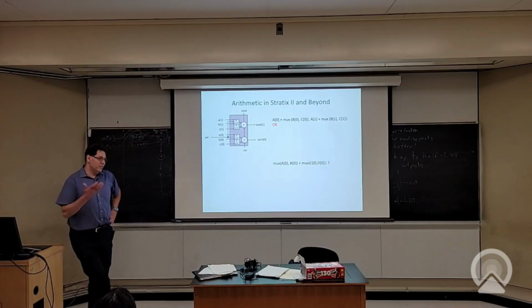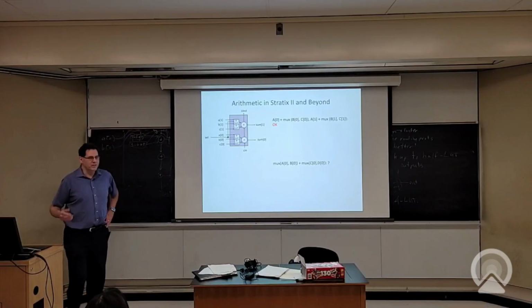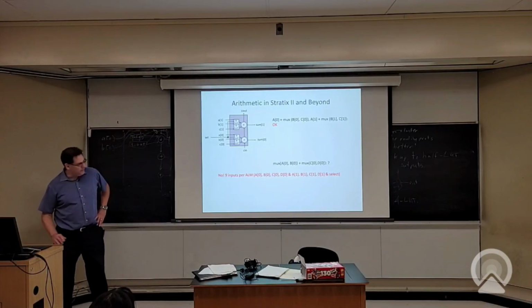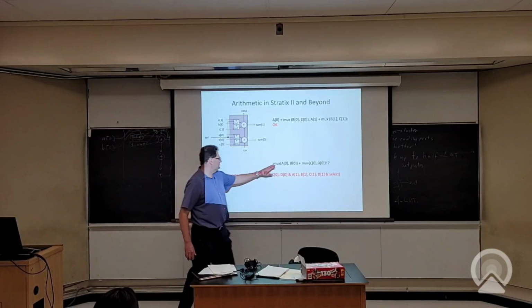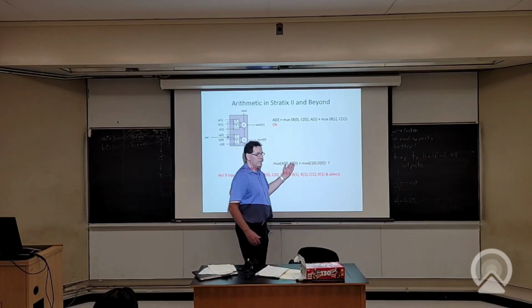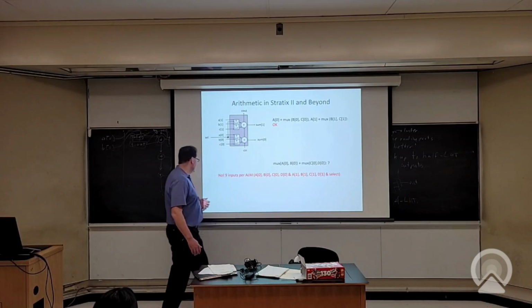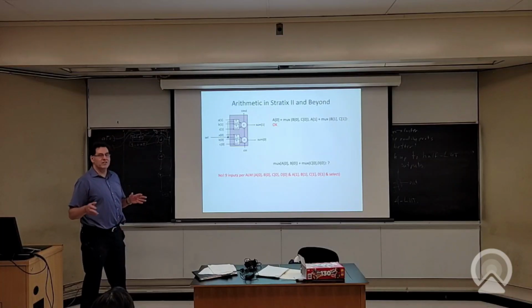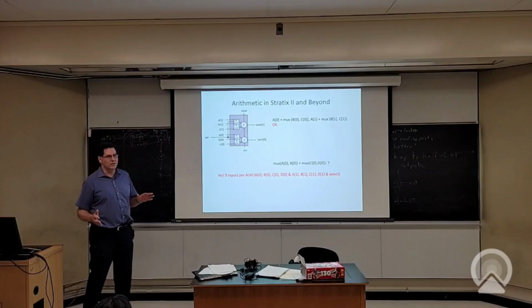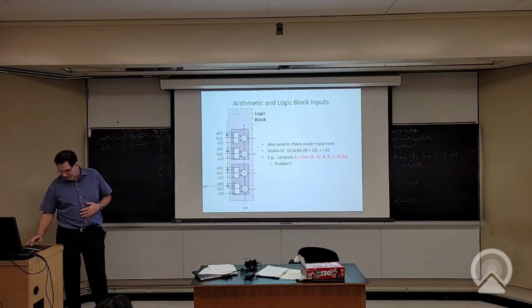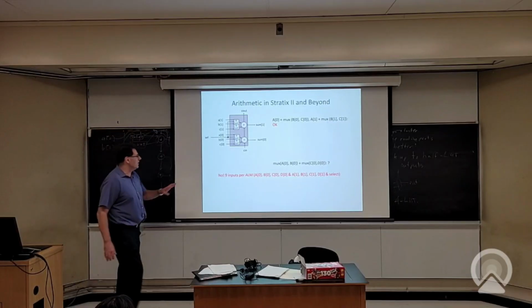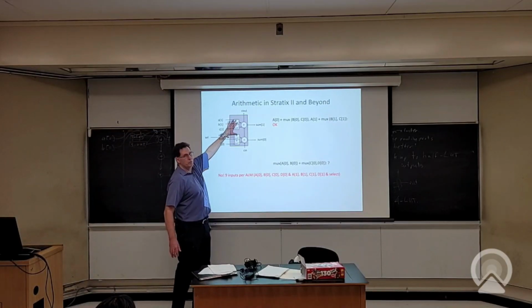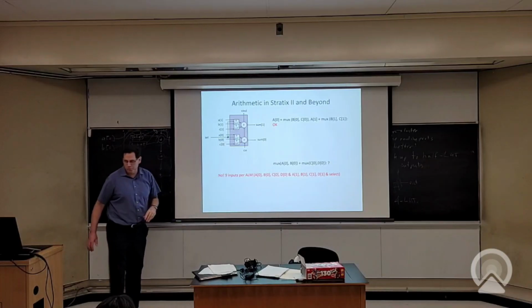Yeah, so my LUTs are fine, but I got a problem with my inputs. Okay, so if I add up all the inputs here, I've got 1, 2, 3, 4, and there's a select signal, actually 2 select signals. Well, I guess if it was a shared select signal, then I have 1. But I have at least 9 signals here. This won't work. But basically, you can get a reasonable amount of logic getting pulled into these LUTs. So it's a good low-cost way to reuse them.